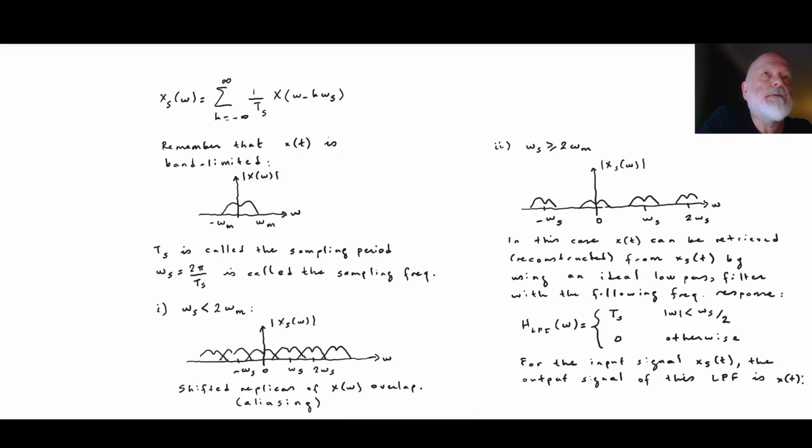Now, the Shannon Sampling Theorem has many different versions and different interpretations. Here, in terms of our analysis, the result, which is known as the Shannon Sampling Theorem, can be stated as follows. If x of t is a band-limited signal, okay, with the highest frequency component chosen as omega m, so its Fourier transform vanishes outside the band from minus omega m to omega m.